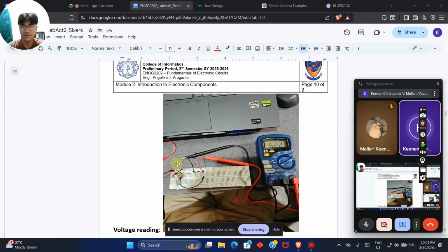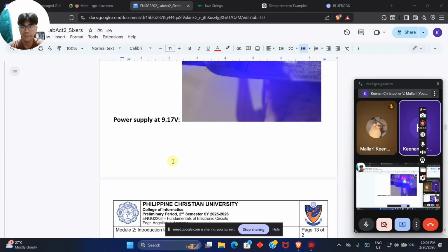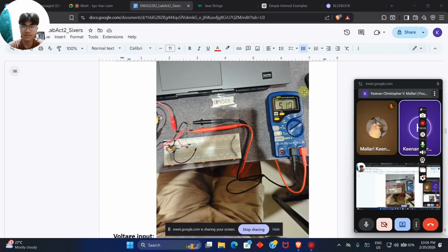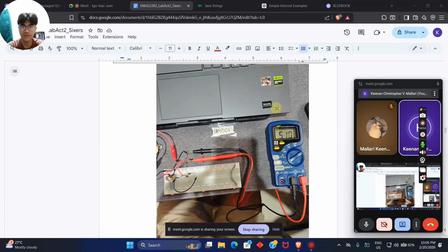And reminder, this video has a lot of scrolling. Here it is to check on the voltage input, and the diode here is showing reverse bias since we flipped it. Here, 0.510 volts. All right. It is confirmed.